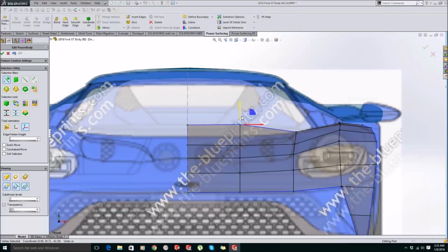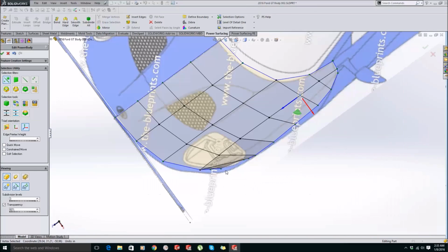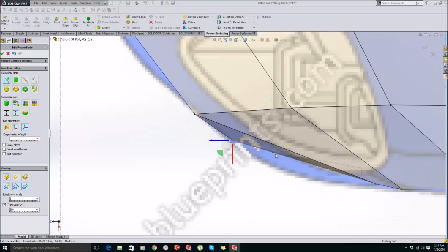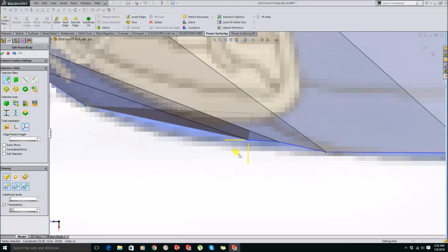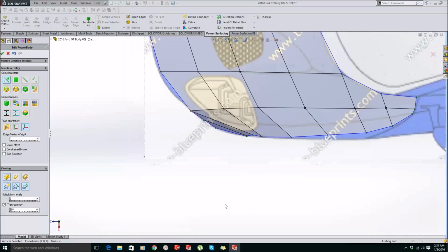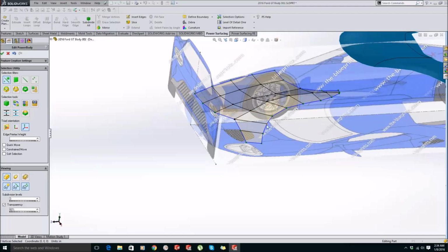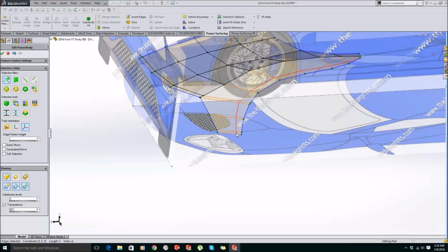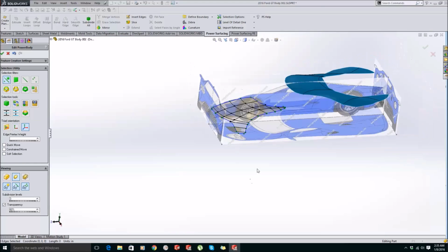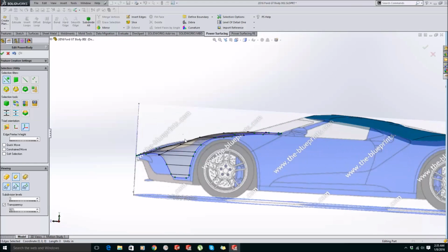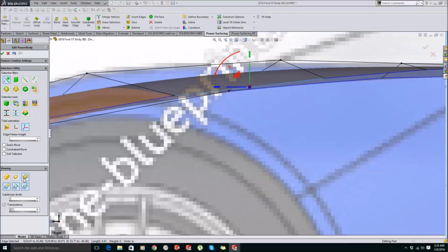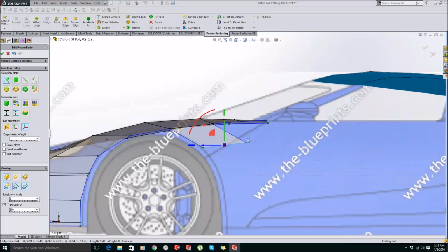Now tuning the shape as per the requirement. You need to know which vertex you need to select to shape the body. You should be very careful while selecting the vertices for shaping. From the top view, you should know which vertex you have selected. For example, I just now needed to change the position of this lower guard, but from the top view I must be careful in selecting the vertex that is linked to that face or edge.